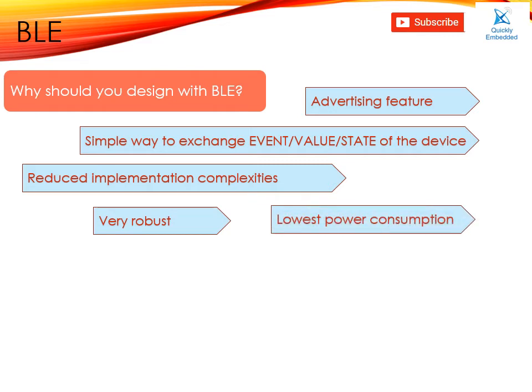The simple star topology reduces implementation complexity significantly in BLE, and it's very robust. A frequency hopping scheme makes BLE highly resistant to interference in its 2.4 GHz license-free band. And BLE has low power consumption and is very secure, through optional 128-bit AES encryption. BLE is known as a widely secured protocol to use in your devices.